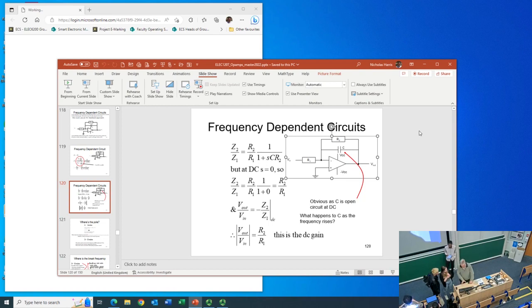It depends what you're plotting. Some people will do a log-log plot, and then you don't officially have a 0, but you get so close to 0 that it doesn't make any difference. Some people will plot a log plot and a linear plot, which allows you to go to 0 and make some kind of approximations on the way. If you're going to plot a proper Bode plot with a log-log response, you go as close to 0 as is sensible. A lot of the time common sense applies: I know what the response is at DC, so I don't need to plot all that way, because that's just causing a great deal of trouble in plotting it. So I won't bother.